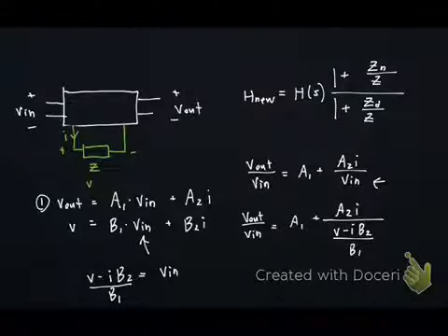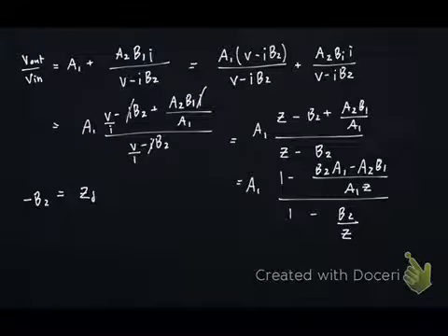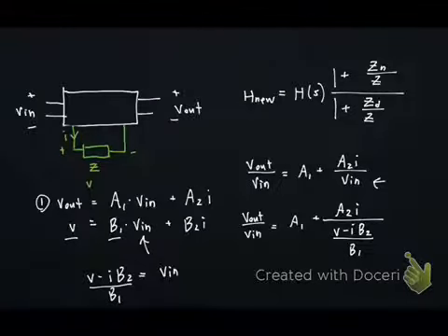Well, if we go back to our original set of linear equations, we have V equals B1 times Vn plus B2 times I. So if we null Vn, if we set it equal to 0, we're left with V equals B2 times I, or V over I equals B2. Now, this V over I is referring to the current and the voltage across the extra element.